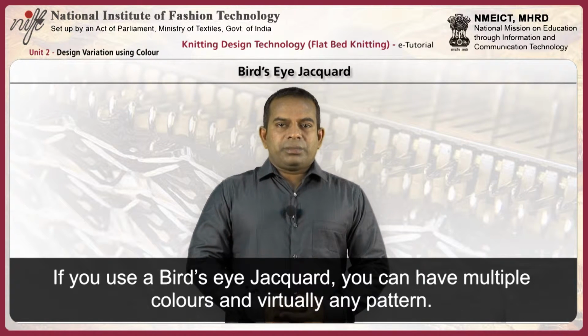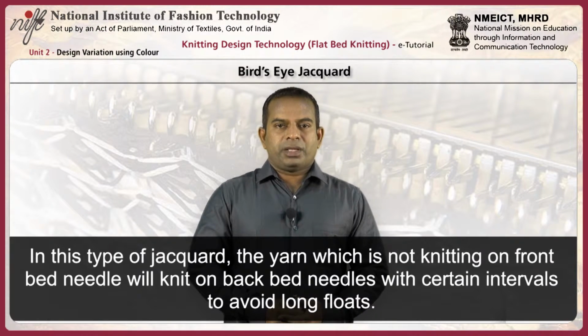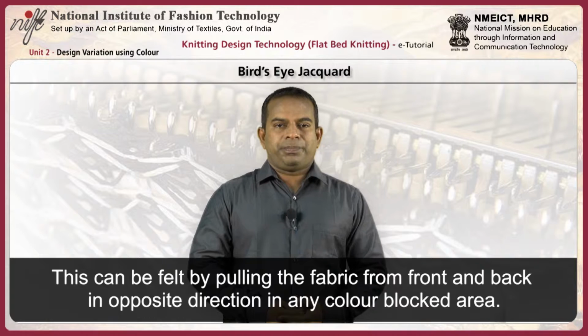If you use a bird's eye jacquard, you can have multiple colors and virtually any pattern. In this type of jacquard, the yarn which is not knitting on the front bed needle will knit on back bed needles with certain intervals to avoid long float. Since all needles at the back side will have some color yarn knitted on it, the floats would be concealed between the front and back knit.